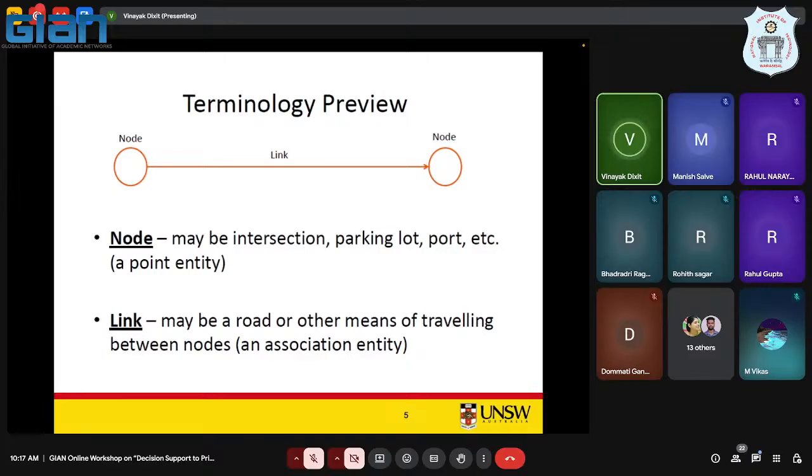It's a very important concept when you're doing your modeling that you want to split up your road network into homogeneous links. Nodes are not only signals or merge points or diverge points. Nodes are places where the link characteristics change. You can have the same thing with railways as well. The link can change from a speed of 70 kilometers per hour to 30 kilometers per hour. So it's two separate links.